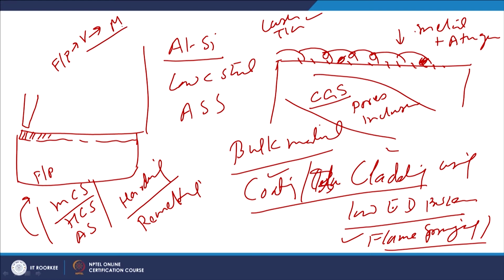So, the remelting will lead to the grain refinement, as well as transformation of austenite into martensite, leading to the production of fine grain martensite plus soft phases like pearlite or ferrite, as per the composition of the steel which is being subjected to the remelting.